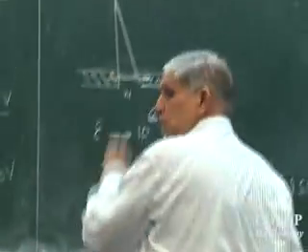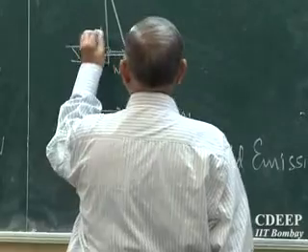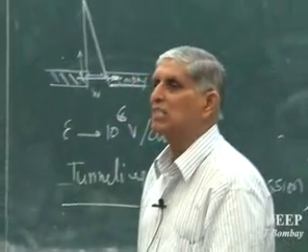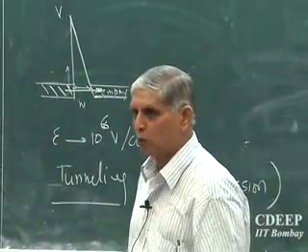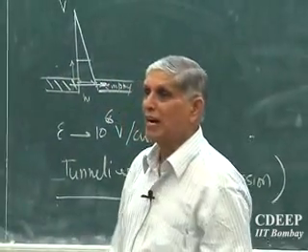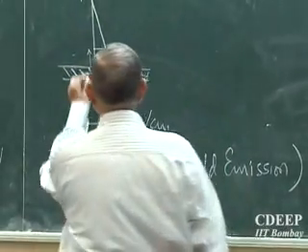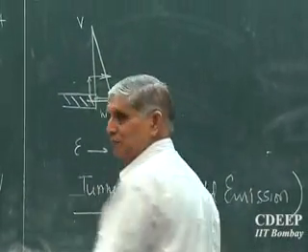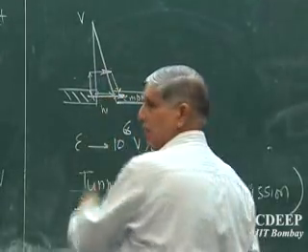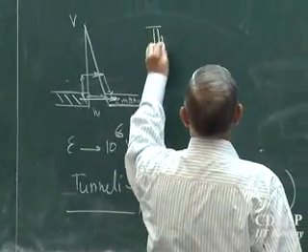There is one more possibility. In this case the barrier may not be small enough, it may be large. Let's say these electrons acquire some energy by applying voltage, but somewhere here it finds a thin enough barrier, so they may actually go and then tunnel and then fall down because of this. This is called thermionic field emission.